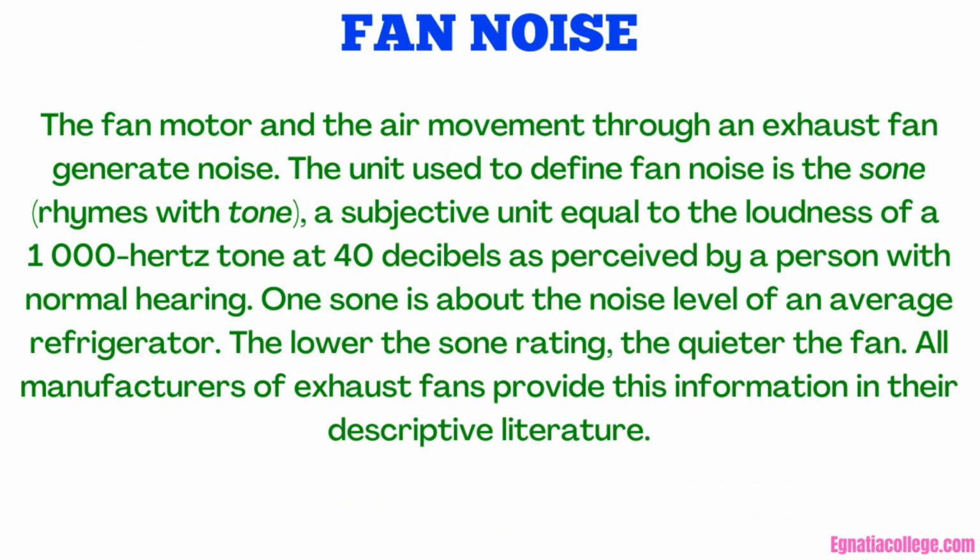Fan noise. The fan motor and the air movement through an exhaust fan generate noise. The unit used to define fan noise is the sone, rhymes with tone, a subjective unit equal to the loudness of a 1000 Hz tone at 40 decibels as perceived by a person with normal hearing. 1 sone is about the noise level of an average refrigerator. The lower the sone rating, the quieter the fan. All manufacturers of exhaust fans provide this information in their descriptive literature.